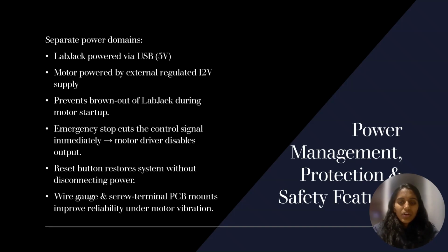Next, the topic is power management, protection, and safety features. For safety and reliability, we separated the power sources. The lab jack is powered from USB, which provides a clean and stable 5 volt, but the motor needs 12 volt and the motor draws a lot of current when starting.